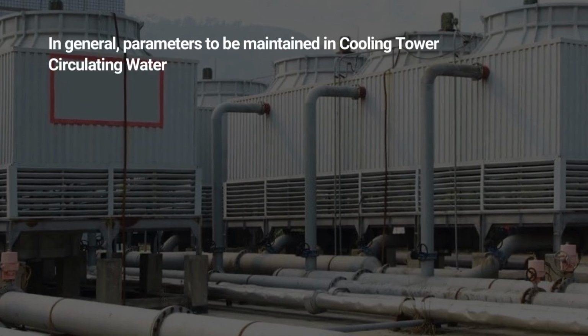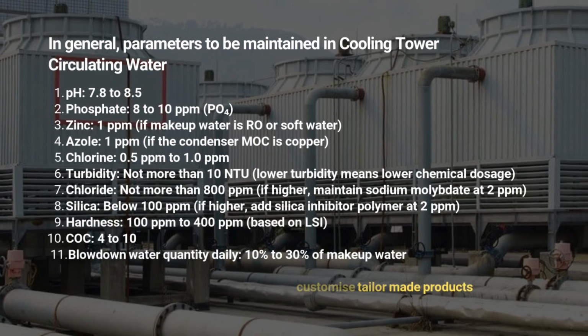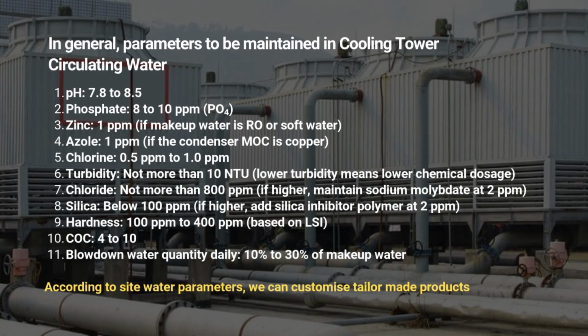In general, parameters to be maintained in cooling tower circulating water. For effective cooling tower operation, key parameters must be maintained. This includes pH between 7.8 to 8.5, phosphate at 8 to 10 ppm, and chlorine at 0.5 to 1.0 ppm. Turbidity should be below 10 NTU. Specific limits exist for chloride, 800 ppm, and silica, 100 ppm, with chemical adjustments if exceeded. Hardness ranges from 100 to 400 ppm, and daily blowdown is 10 to 30% of makeup water.